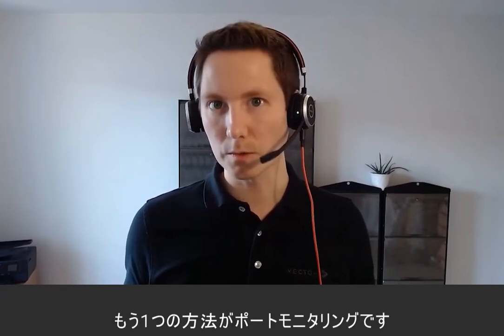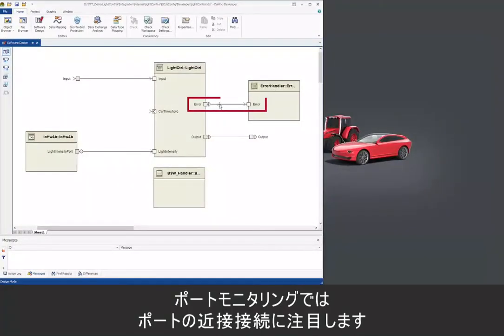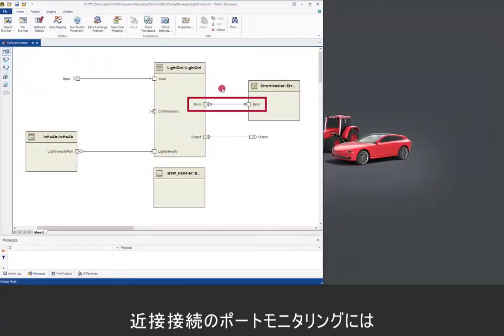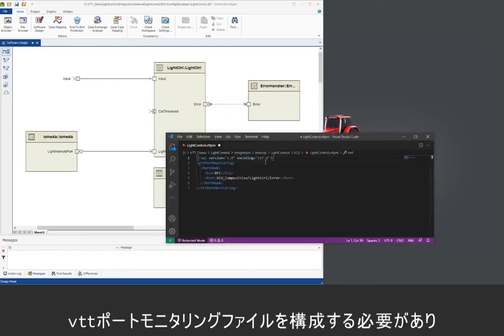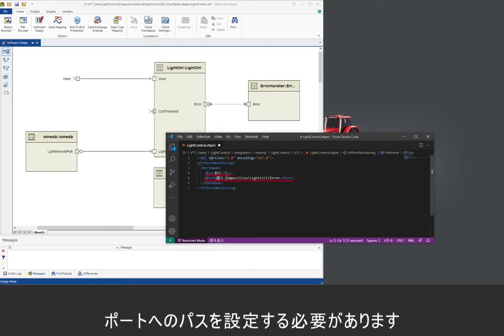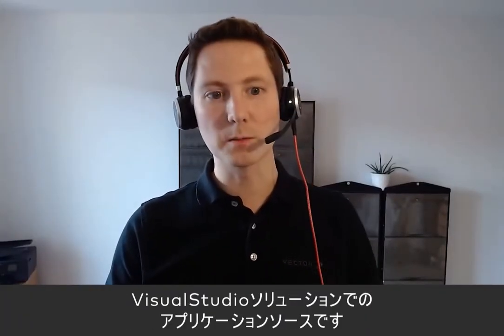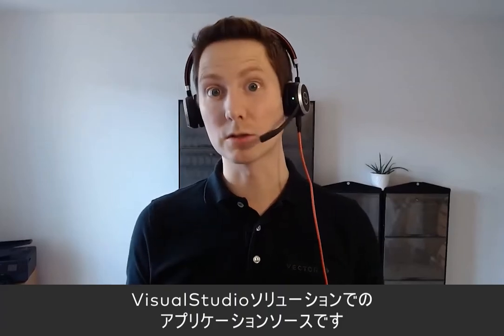Another way is the port monitoring. In port monitoring, we are focusing on closed port connections. And here, to monitor closed port connections, you have to configure the VTTPM file, the VTT port monitoring file. And in that, you have to define the ECU and the port path to the port that you want to monitor. Okay. Then let's take a look at the Visual Studio solution created by vVirtual Target, or the application sources.